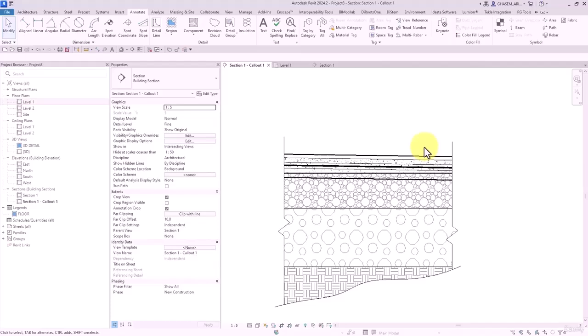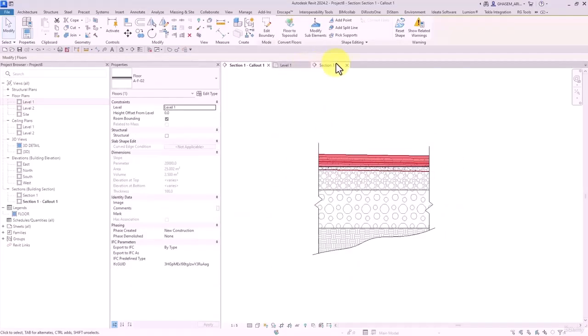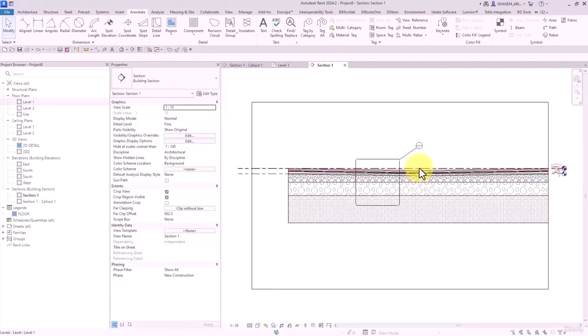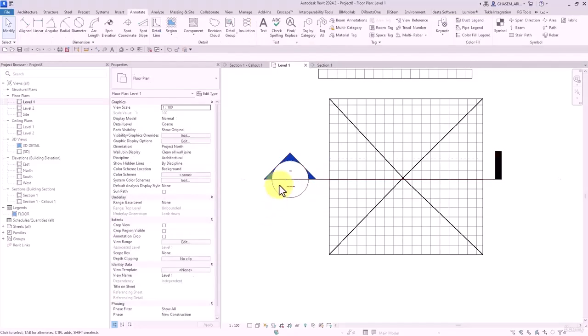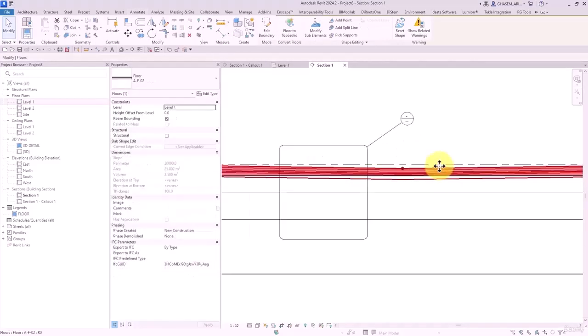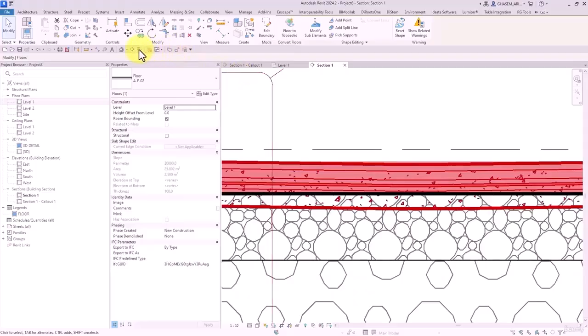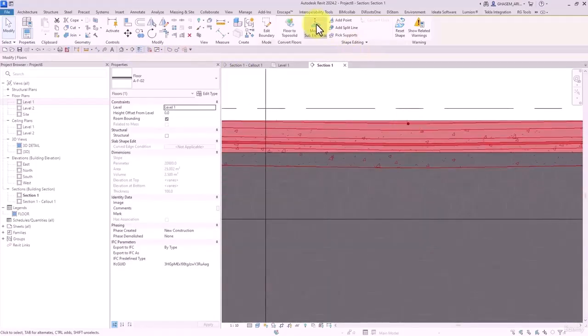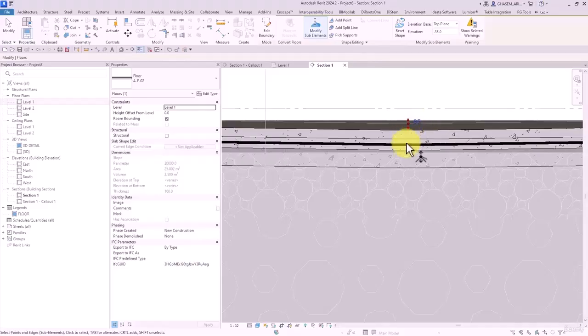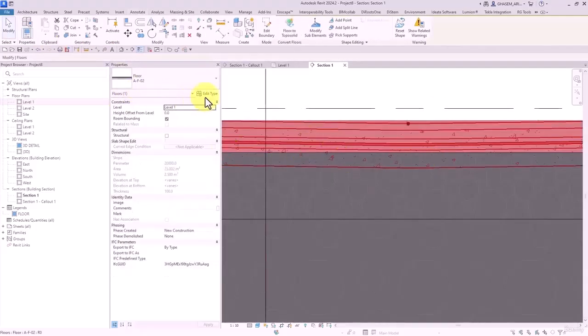It's a warning about highlighted floor overlappings. And it makes sense. Let's see, where is this line? Okay, let me move this section line here. As I said, it's normal. The reason is that here we had 35 millimeters and it's moved for 35 millimeters and there is an overlapping because of this motion and it caused that warning.